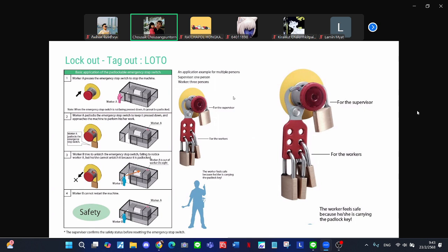It consists of two words: lockout and tagout. Lockout means physically shutting off the machine's energy source. If we're talking about the power source, it's not only electrical; it may be hydraulic or pneumatic power too. It is locked to the off position using a special lock tool, as you can see in this picture.